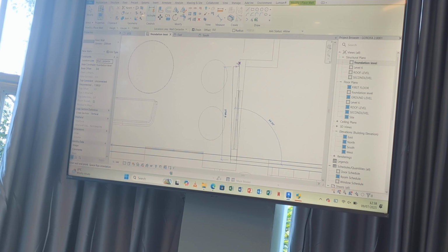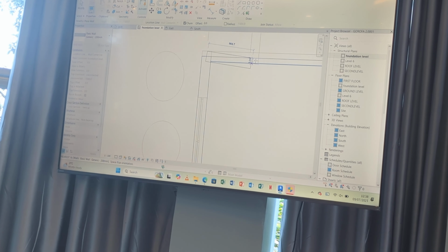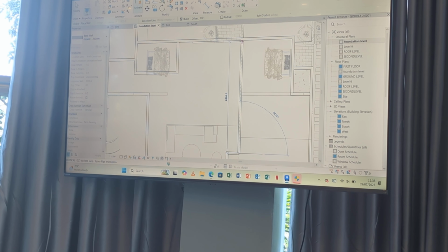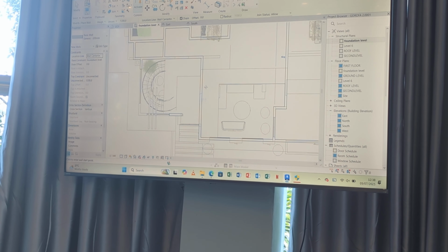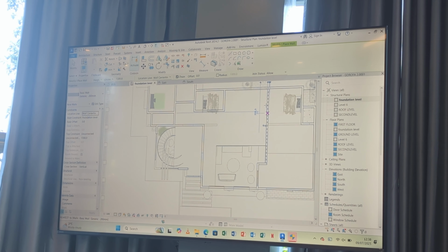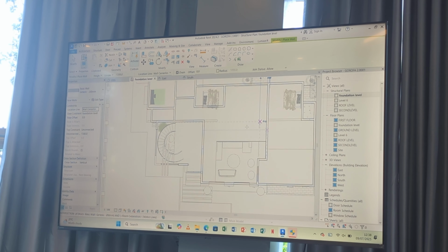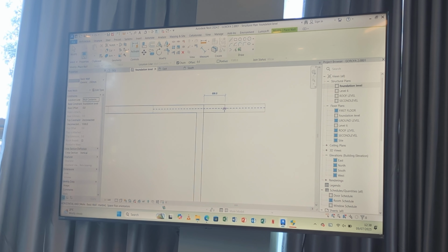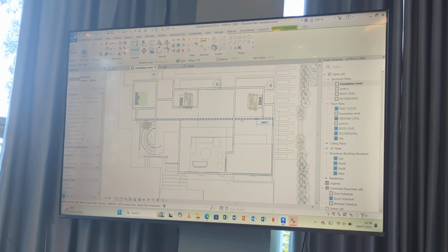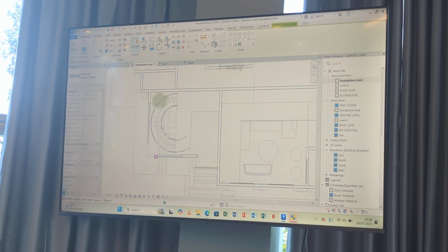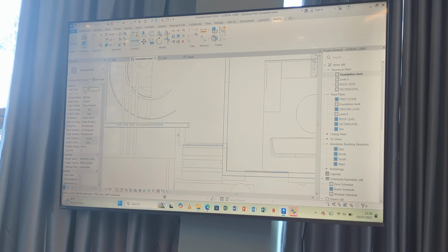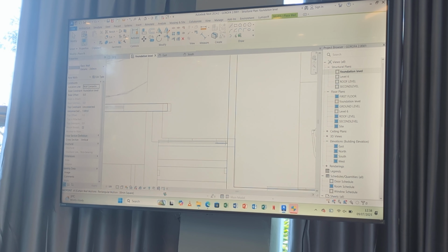So all my interior rooms, I have done them, all the exterior walls. Make sure you've done all the exterior walls, all the main walls. If this is supposed to join somewhere, let it join. All the partitions and the cuttings, they will do them up. Because you may have your ground floor all here with no wall to support, and yet your first floor has walls in the middle, your structure is going to fail. So this closes up there, that's a curtain window, this will close off here, this is the main door.